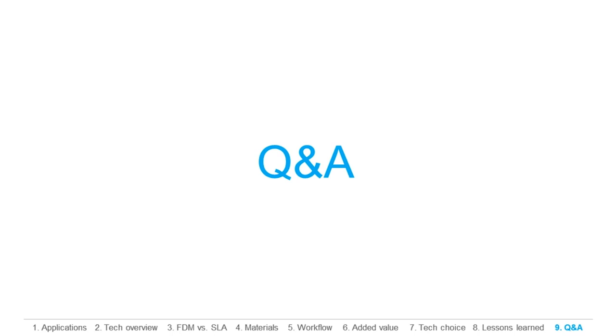Chris is absolutely right. I think for small batch manufacturing, 3D printing injection molds is certainly viable, and for larger production requirements, I think our SLS machine would also be an option depending on what material requirements you need. But for the thousands and hundreds of thousands, you're probably looking at injection molding as the best option.